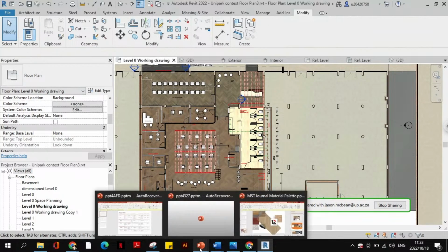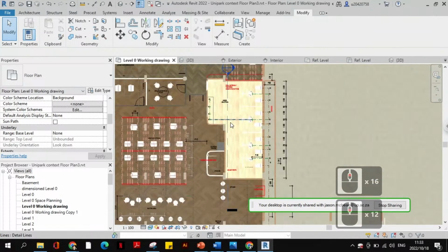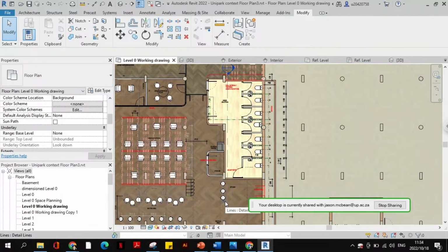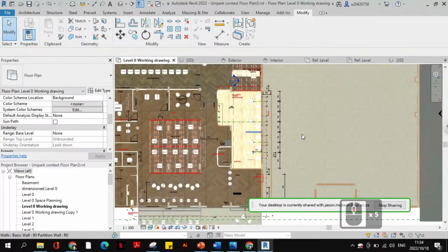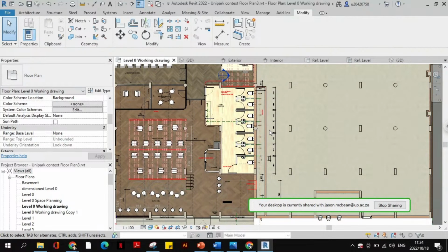I'll go and look for creating door families on Google. There's lots of them, and creating curtain wall panels. But the workflow that I showed you, you adopt the same thing, but without the frame. There's lots of videos to help you guys. But please try, and come and see me. In the meantime, draft or model in place. You can punch an opening and model the door in place. Worst case. Okay. Cool.